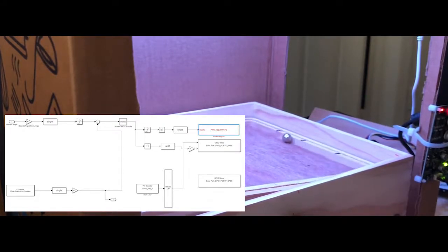The motor controller actually works using a desired angle and the feedback from the quadrature counter chip that we have on our board in order to output a desired PWM that moves the motor to a certain position and stops it once it gets to that position.